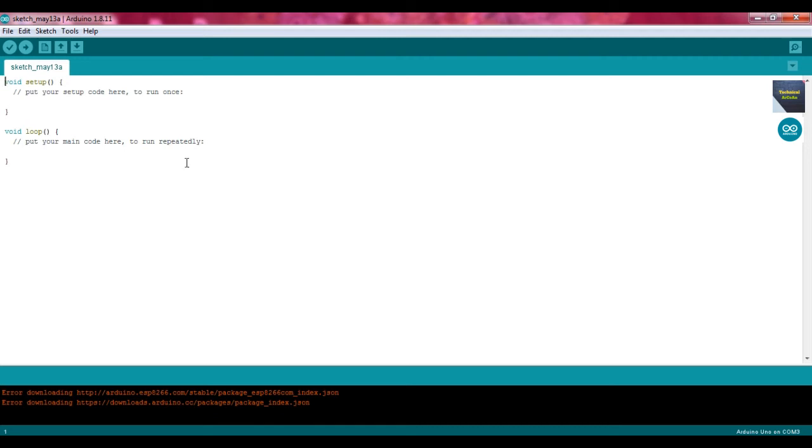As far as Arduino programming is concerned, it actually consists of three parts. The first part is for libraries, declarations, variables, constants, and routines. The second part is the void setup, which performs only once at the starting time. And the next structure is your void loop. It performs repeatedly until power is shut off or the reset button is pressed. That means whatever code your Arduino sketch contains, you should write within the setup or the loop structure.